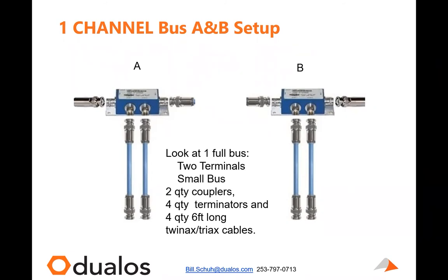You really don't want to do that because when you connect to a bus coupler, you have, in the first order, a voltage divider. When you go through the bus coupler, there are a couple of series resistors before it touches the backplane or the bus cables, and then a couple of series resistors again. So coming on the input to a device that might be right next to you, it's at approximately 1/3 the amplitude as opposed to the full amplitude.